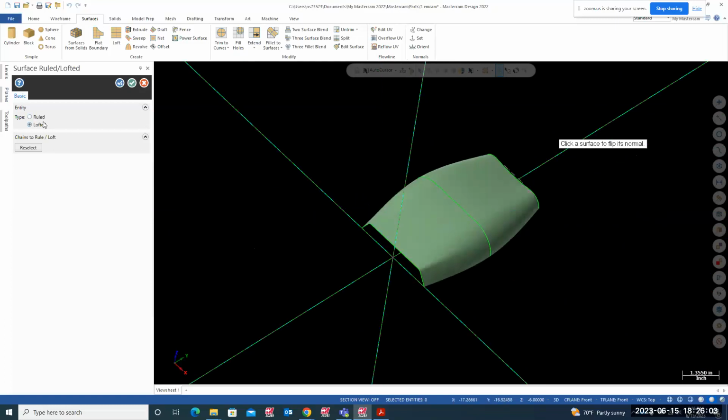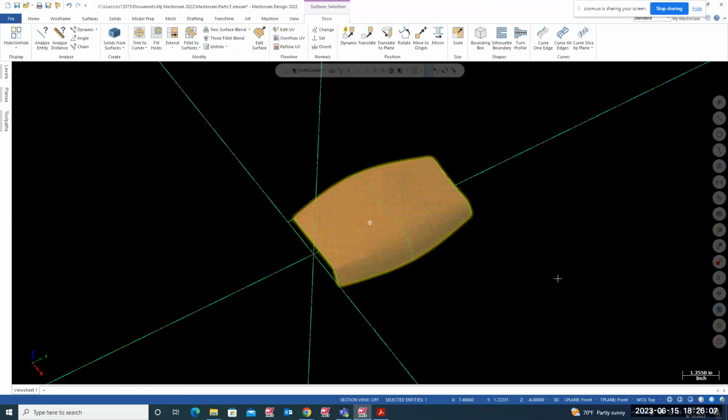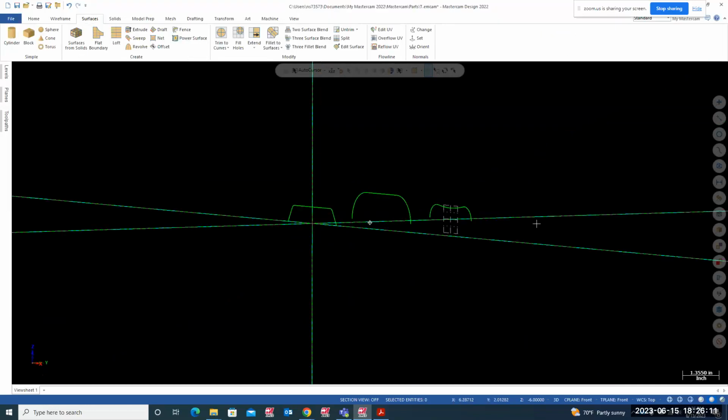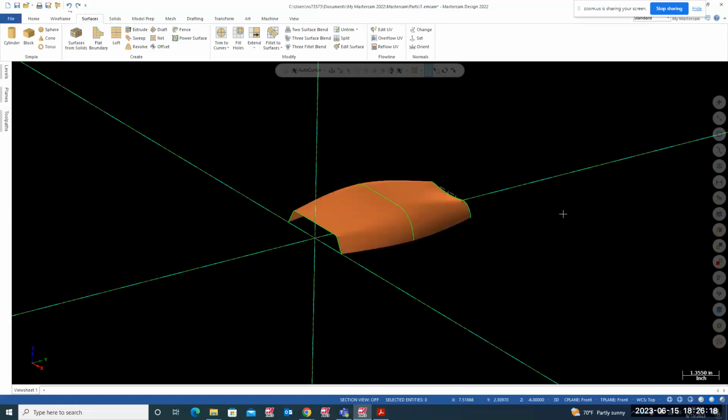So if you pick loft surface, guys, it's just one surface. Look at that. I select the one surface. If you want to delete, you can delete this whole surface. There are not individual surfaces between individual contours. Undo it. It's only one surface.